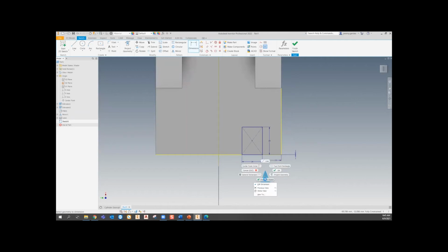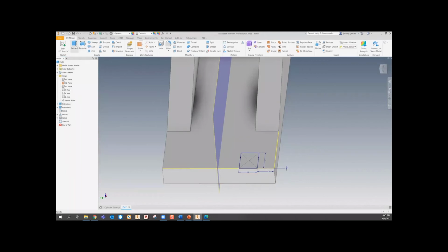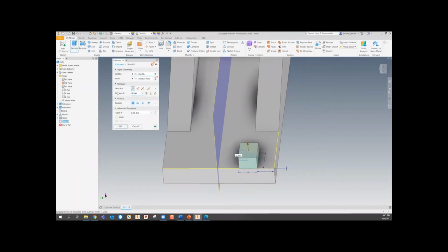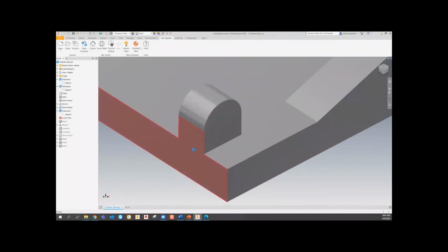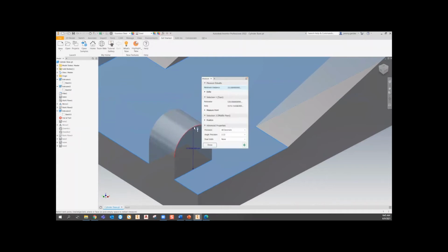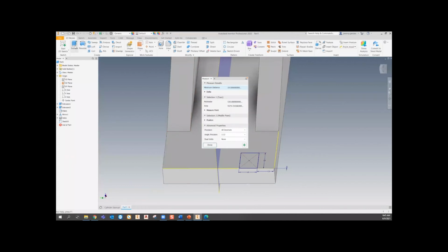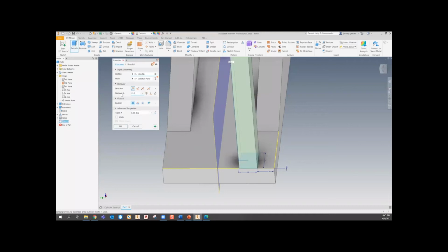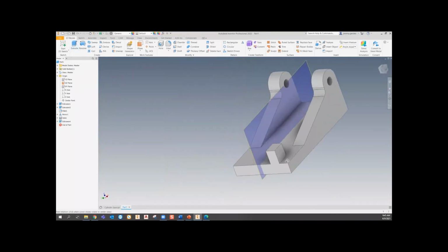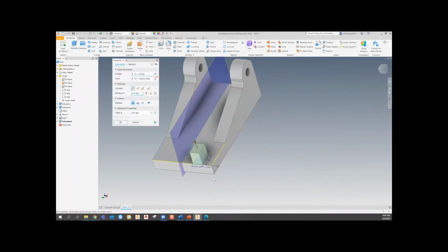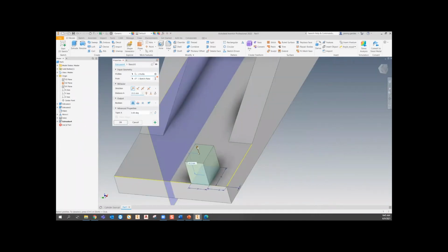So we'll say finish sketch. Then we'll extrude it, and that is going to be 34.5. No. What is that? Metrics. Measure from there. 19.5. And say you don't know what the dimension is, or you're trying to figure out what roughly is going to fit best, you can grab the arrow and manually drag it and place it.